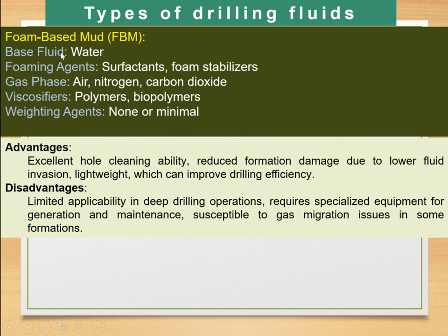Foam based means the base fluid is water, and gas will also be added. Foaming agent means surfactants, foam stabilizers. Gas phase is air, nitrogen, carbon dioxide. Viscosifier is polymers, biopolymers. Weighing agent none or minimal. That means foam based muds will be required in which condition? When formational fluid pressure is very low. These kinds of conditions will require the introduction of foam based muds.